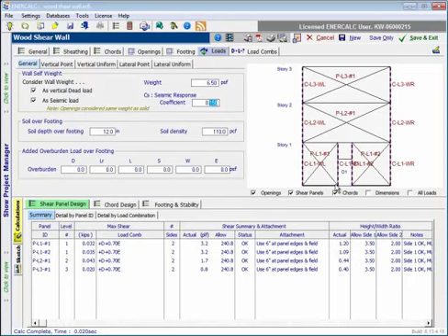that location. So as a simplification, and to try to save you a little bit of extra work of having to model any potential other loads, what we've done is we've simply said, in general, wood frame shear wall construction is relatively light enough that we can simplify it and say that the weight that we're assuming for that construction is approximately equal to the weight of whatever is going to replace or fill that opening, whether it's a door, a louver, a window, etc. So that is important to understand and hopefully convenient.